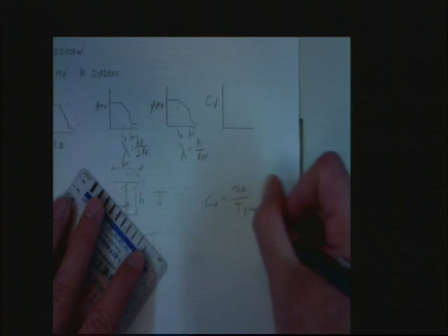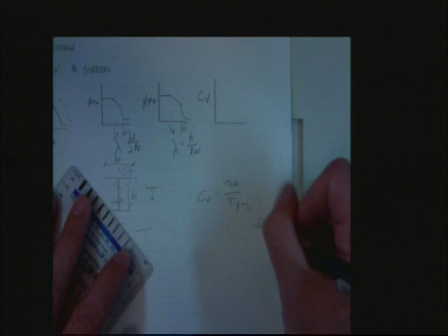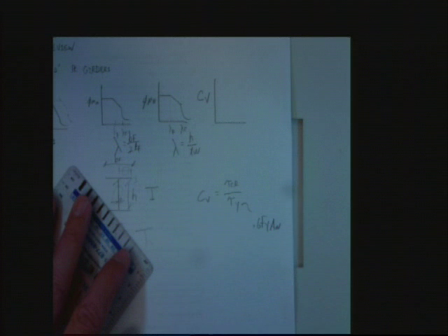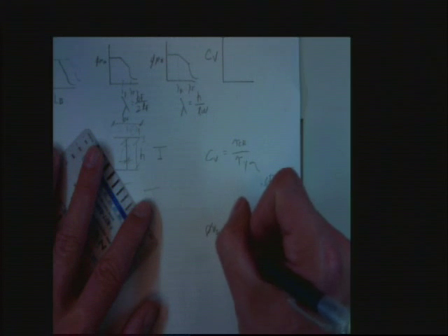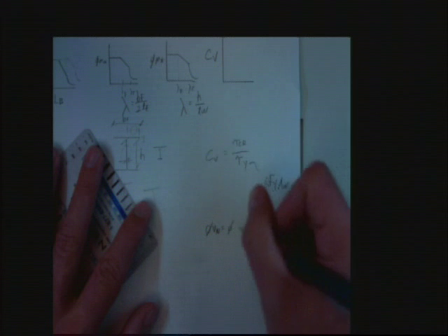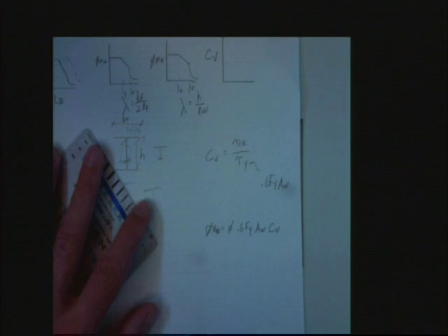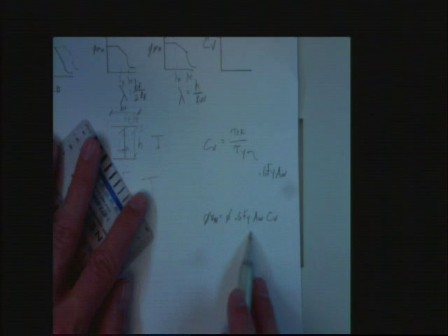And this value, this tau sub y, does anyone know what that is? 0.6 Fy AW. You with me? So what's common is to express this as phi Vn is equal to phi 0.6 Fy AW C sub V. C sub V, all it's going to do is reduce this. You with me? Makes sense? Okay, we're going to come back to this equation in just a second.